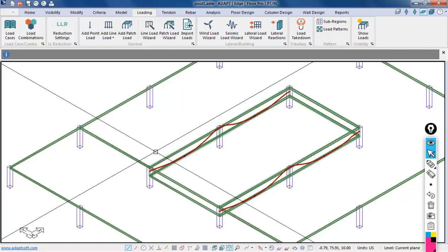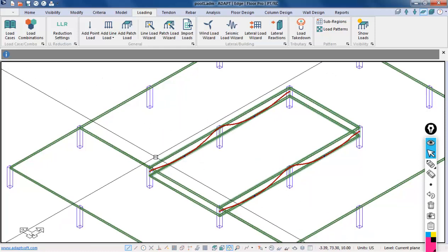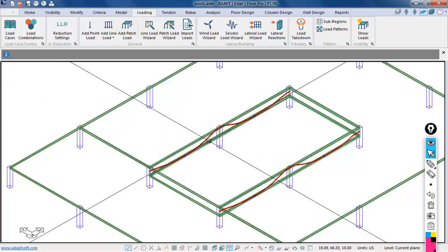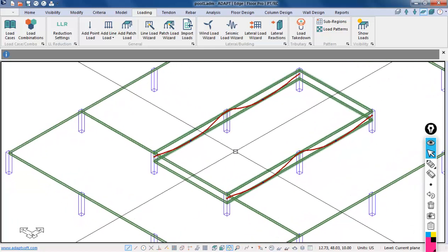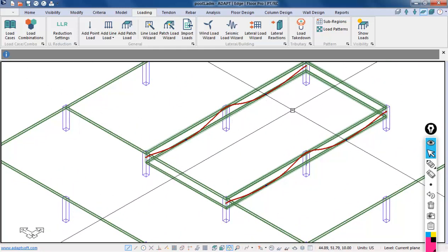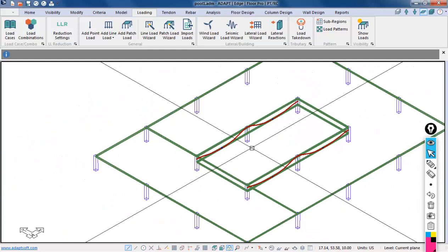In addition to that, because the tendon exits the slab and it's not technically recognized within the wall, you essentially are forced to use an effective force method for assuming the post tensioning in those members.